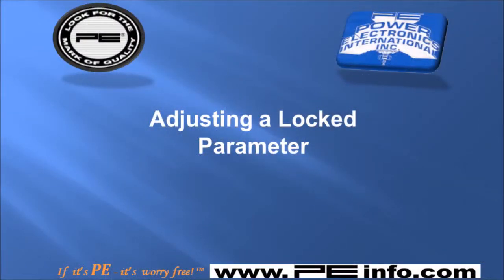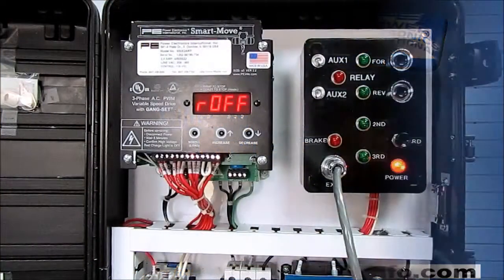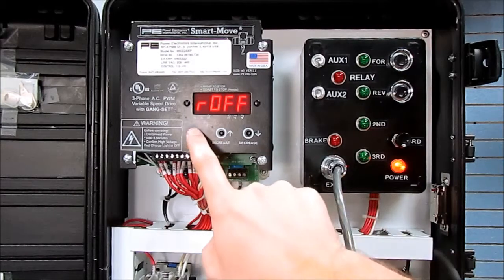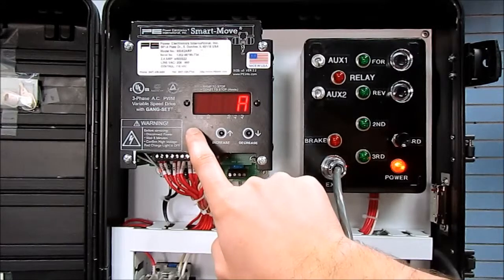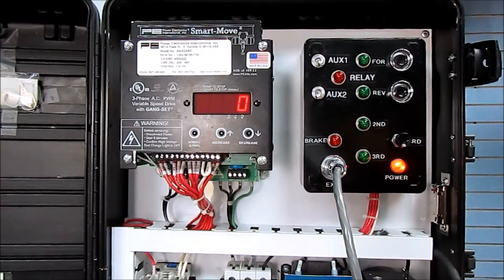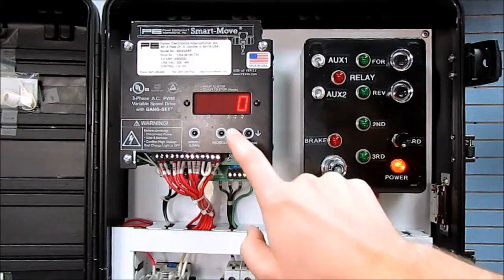Some of the parameter groups are locked to prevent accidental changes. On this drive model, the L and the U parameters are locked. Let's say that you wanted to adjust parameter L10. Just like before, you first hold down the scroll button until you get to the L parameters. Notice that you are now at L0.